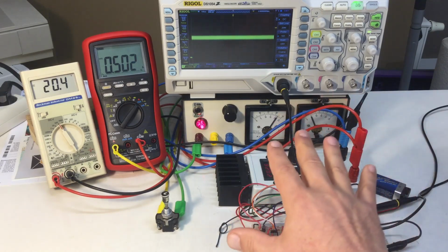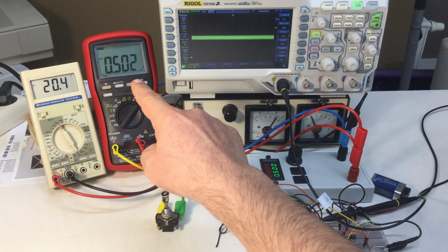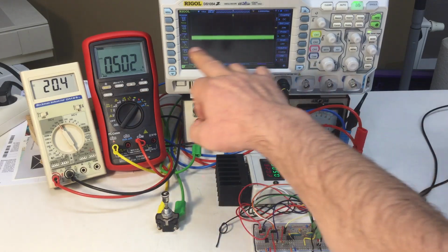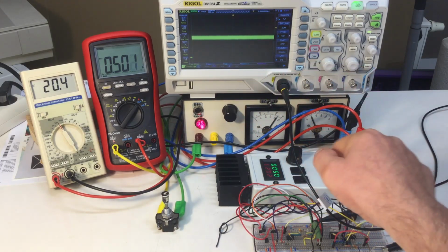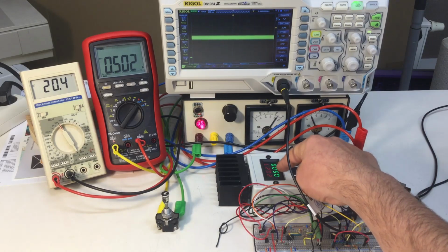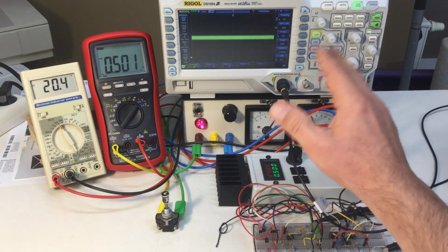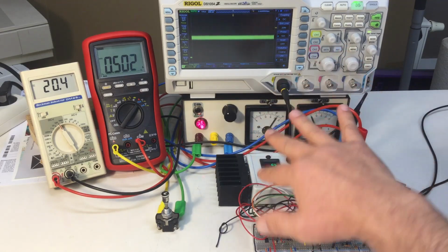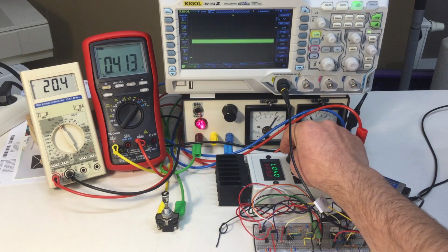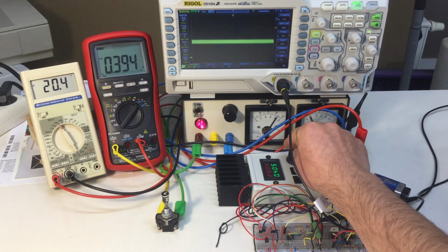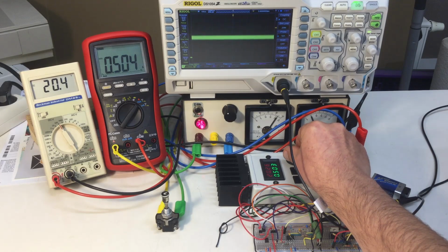Currently, the whole thing runs in a steady state. That is, at 20 volts, 500 milliamps. And this is just the voltage drop across the shunt resistor, including the second shunt in the ammeter. So, if that is a steady state, what is a transient? A transient is simply a change from one steady state into another. Like, I'm decreasing the current to 400 milliamps or increasing the current again to 500 milliamps.